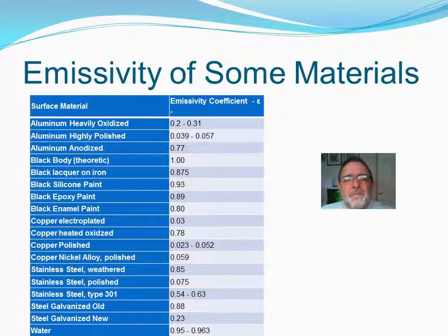And here's what we mean. You'll notice that the black enamel paint has an emissivity of 0.8. It's about in the middle of this chart. You've seen this chart before. It's important not to memorize all of it, but to understand the concept, but to know those things that you're looking at. So that's why we painted that device, which you'll see in a minute again. You'll see me reflecting off of it. That's why we painted black spots with enamel paint. We knew exactly what the emissivity was, could make our measurements and metrics of how much energy was being used accurately because of that.